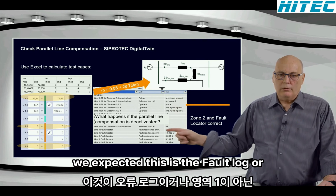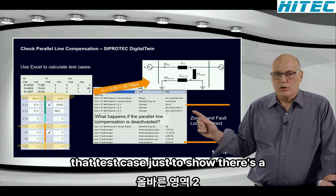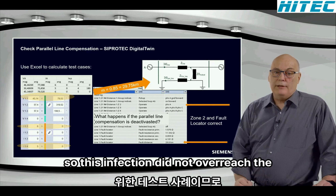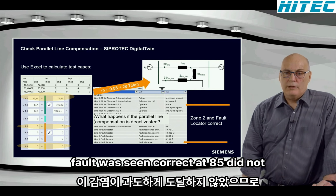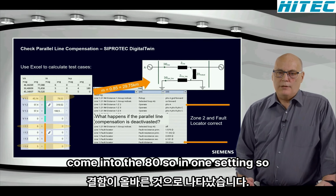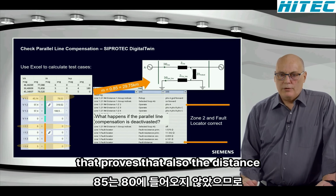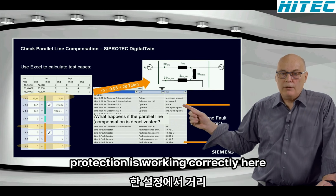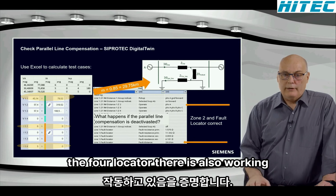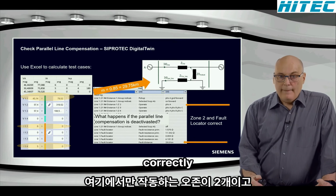This is the fault log for that test case, just to show there's a correct zone 2 operation, not zone 1. So distance protection did not overreach. The fault was seen correctly at 85%, did not come into the 80% zone 1 setting. So that proves that the distance protection is working correctly here. Only a zone 2 operate, no zone 1. And the fault locator there is also working correctly.